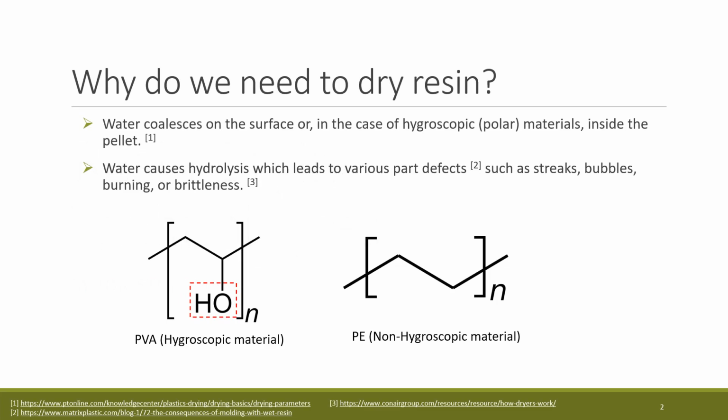So what is the purpose of drying our resin? Most of the polymers that we use in the lab collect moisture from the air that coalesces on or inside the pellets themselves. Hygroscopic, or polar, materials tend to absorb some moisture into them due to the material and water having strong secondary forces.